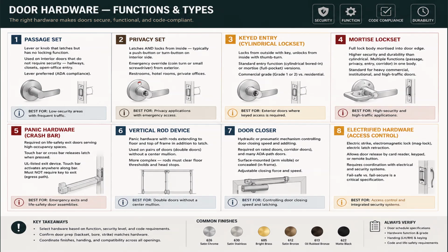Electrified hardware is access control: an electric strike, an electromagnetic lock, a maglock, or electric latch retraction. It allows door release via card reader, keypad, or remote button, and requires coordination with the electrical and security systems.